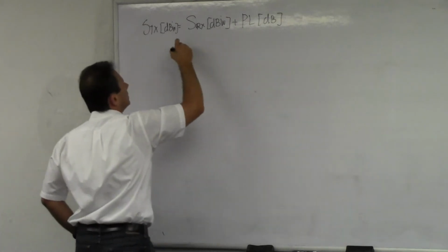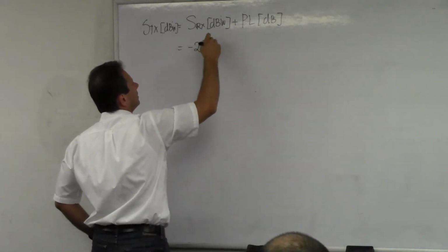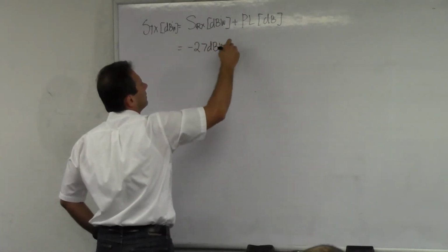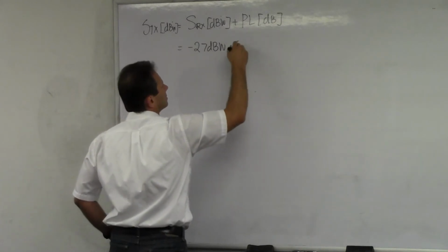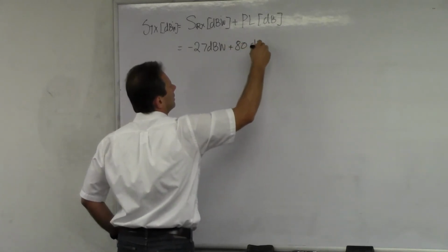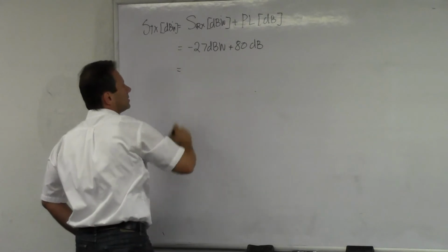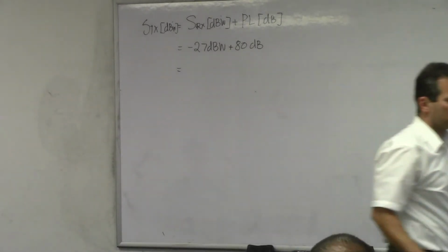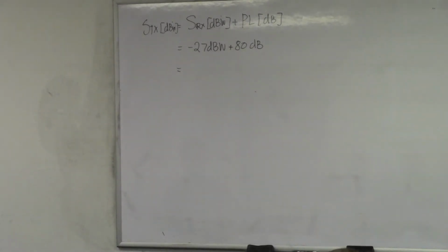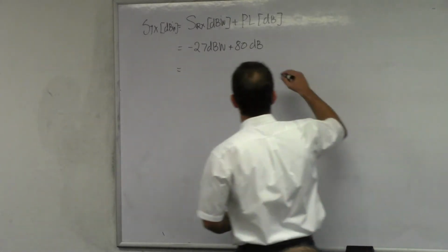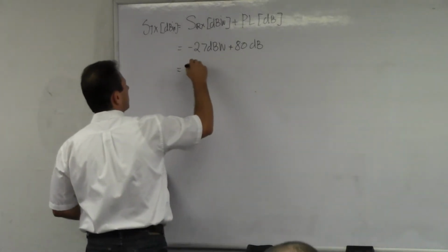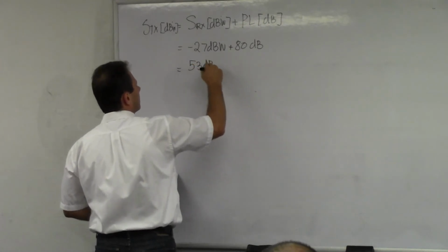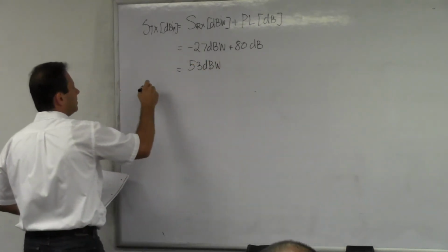In our case, this becomes minus 27 dB watt plus path loss of 80 dB, and this gives us positive, 53 dB watt.